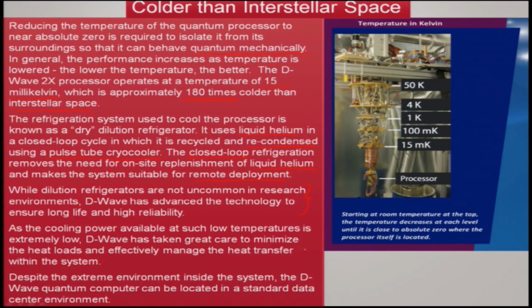While dilution refrigerators are not uncommon in research environments, DWave has advanced the technology to ensure long life and reliability, and this is one of their technology developments which has made this kind of quantum computer possible. As the cooling power available at such low temperatures is extremely low, DWave has taken great care to minimize the heat loads and efficiently manage the heat transfer within the system. So, these are design aspects that they had to engineer to ensure that such a system can operate at such very low temperatures and sustain it there.